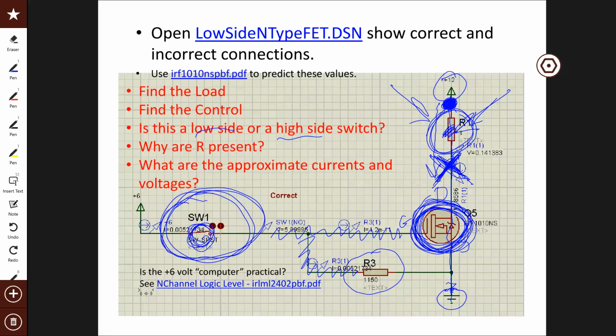If there's an electrical storm or some sort of electromagnetic wave coming through the factory or whatever, you might fluctuate the voltage on this wire because nothing is holding it high, nothing's holding it low. And what could happen is noise could drive this voltage up because nothing is holding it down. And so your FET could just accidentally turn on when you have an electrical storm.